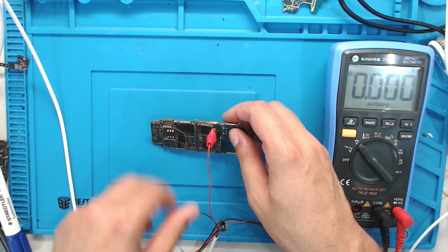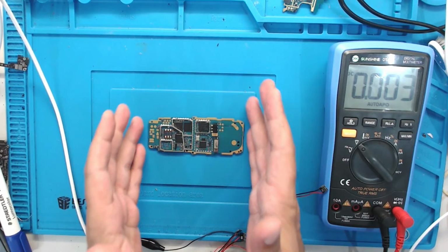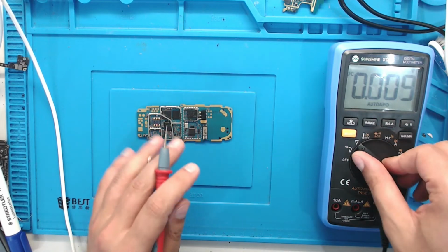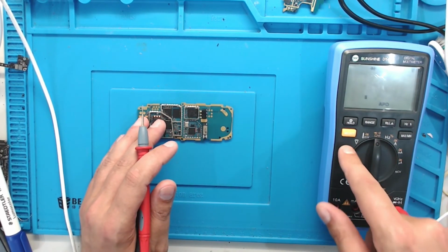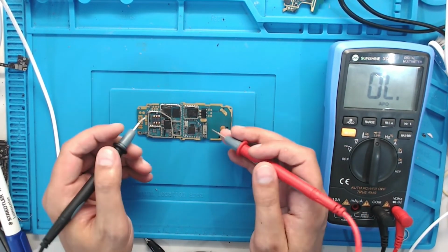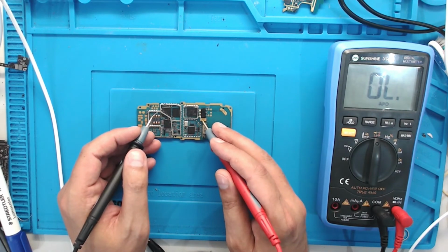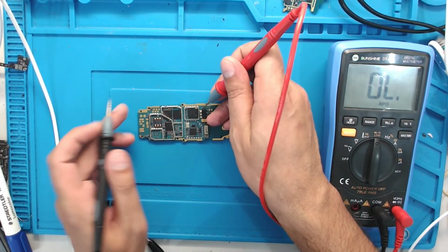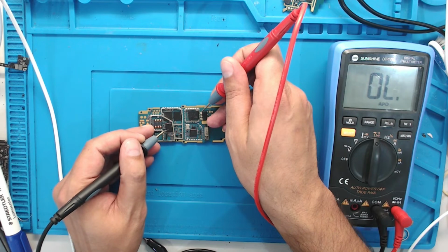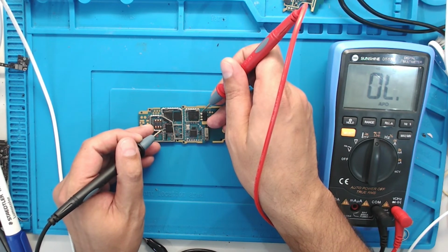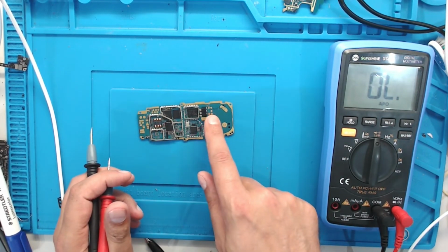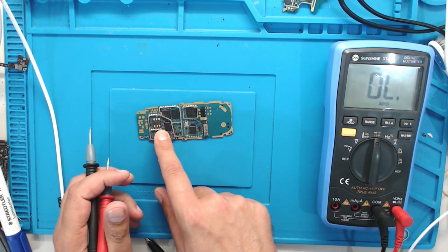But this is very important to know: this mainboard has one-way voltage or two-side main voltage. That is very easy and simple, I'll just tell you. I bring a multimeter on the buzzer test, continuity buzzer. Put one cable on the positive side of the charge port, and we find the 4 volts voltage on the PMU, the power management unit. If you hear the beep, that means this mainboard has one-way voltage, coming directly from here to the power management unit.